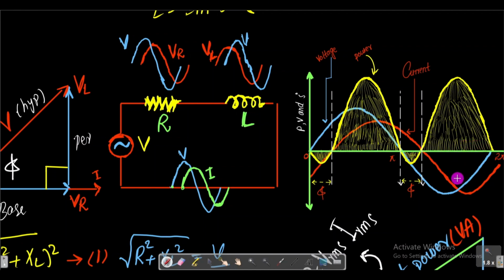And in this case this current is negative, and this voltage is also negative. If we multiply negative with negative, the resultant will be positive. This is the graphical representation of the power, which is positive. If we multiply the amplitude of this current and voltage at each and every degree, it will give us some data points, and if we plot that, it will give us such a type of power.